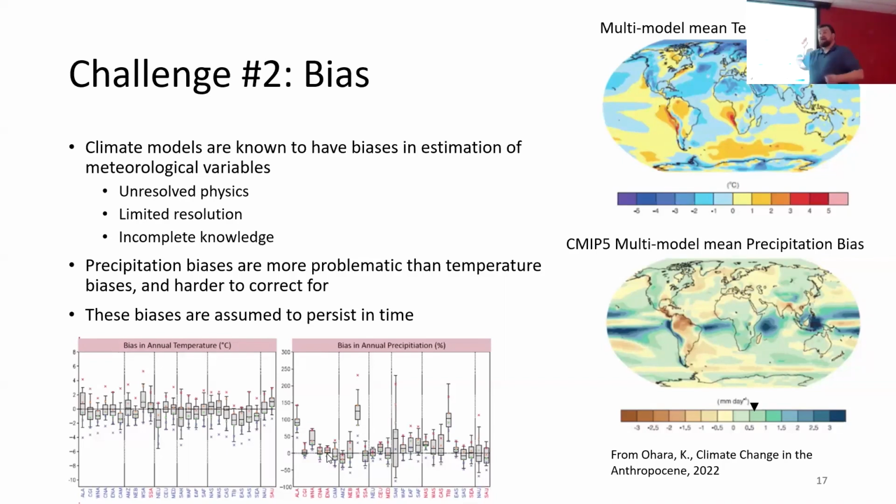So we're taking the mean of an error over time and over models, and we still can get, in Canada, roughly a 0.75 millimeter per day bias, which manifests as an annual error of 275 millimeters, which is as much as 30% of the water budget of many of the places in Canada. And that's for an annual average. And then we want to be able to make predictions about events. And so this is a big deal.